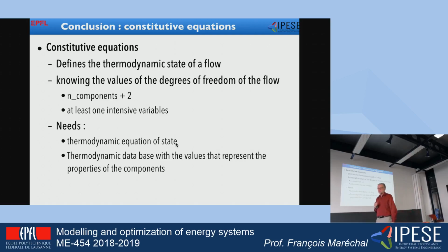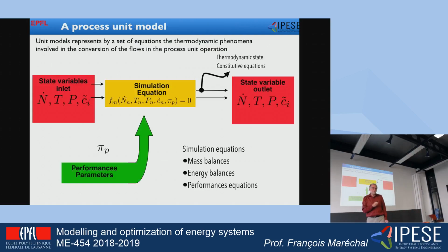And from there, you will be able to apply the calculation of the equations of the process units, because now you will know the state here, with the enthalpy, with the entropy, etc. And you will be able to calculate how the states have been transformed by applying the mass and the energy balances, but also by representing the performance equation.